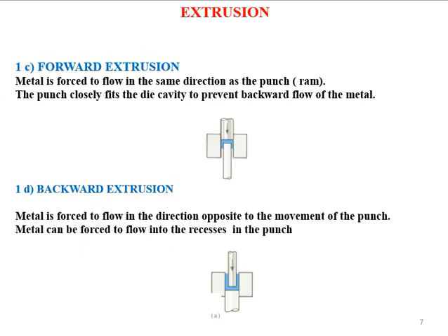Now, in a similar aspect, from the figures of direct and indirect extrusion we can infer that we get solid objects, right? What if we require hollow parts? We need to fabricate hollow parts. In that aspect, we slightly modify the configuration of the system that we are using, right?